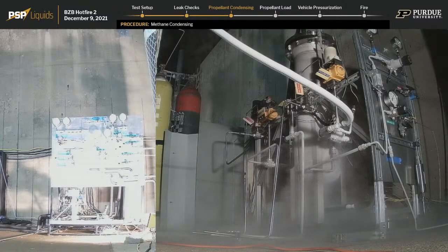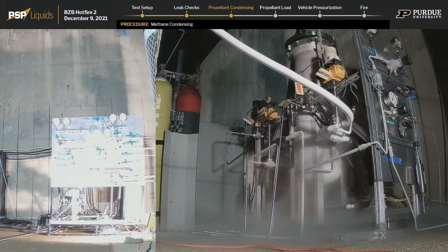One of the things that we are having happen now is stuff is starting to get really cold. Actually, sure. Why not use closed loop control for the condenser? Well, this is another example of how we had to adapt quickly to a new set of challenges. We originally did not plan to use a liquid methane condensing system. However, due to supply chain related issues, we decided to move from directly acquiring liquid methane to condensing it ourselves using gaseous bottles.